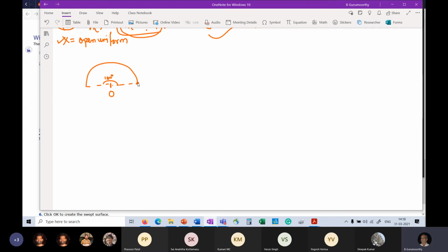You know two things, which is the endpoint P0 and the other endpoint. I'm going to call this 2 right now because we are interested in a quadratic Bezier, or a quadratic curve, so I can get away with the smallest. So K still remains what it was earlier. K is 3. And therefore, the smallest value of n that you can start with is 2, so that n plus 1 is equal to K. And so you get a single segment, which is this curve.